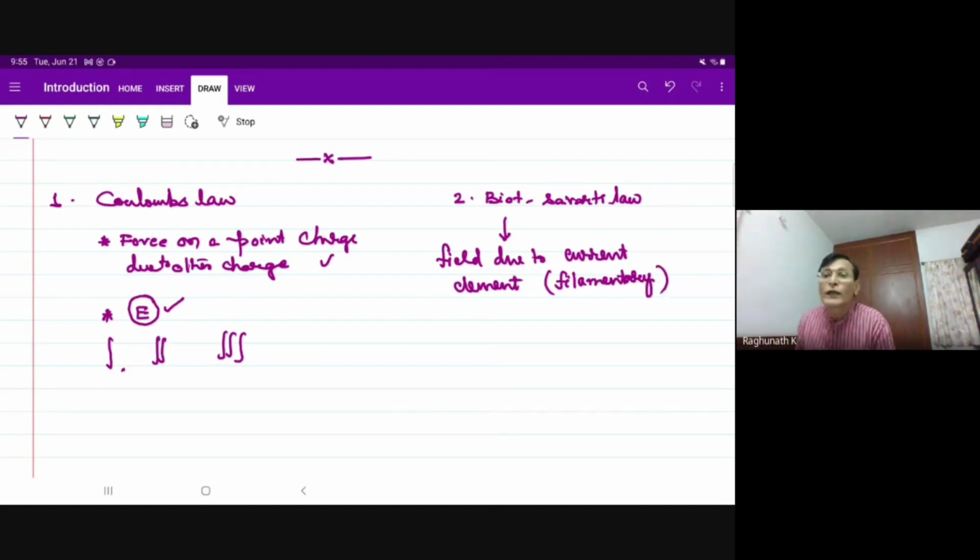No current is filamentary for us, because it's a conductor of finite dimensions or a surface of finite dimensions that we'll have. Nowhere will I see filamentary current, because I cannot have a conductor tending to zero radius. For that current, I will first know the field at any point because of the Biot-Savart law. Somebody gave it to me; ultimately these are verified to be correct later on. I will try to reason out why the different terms are there, but still I will know this to explain it.